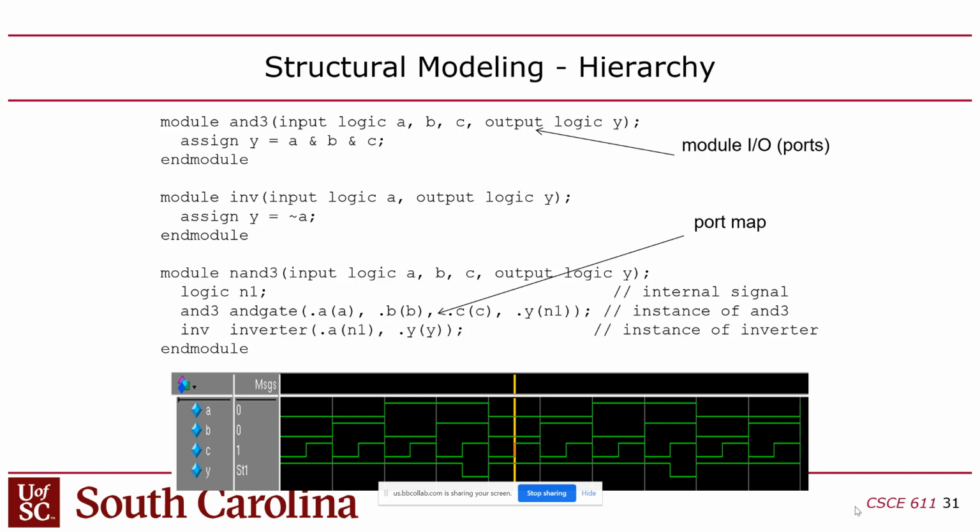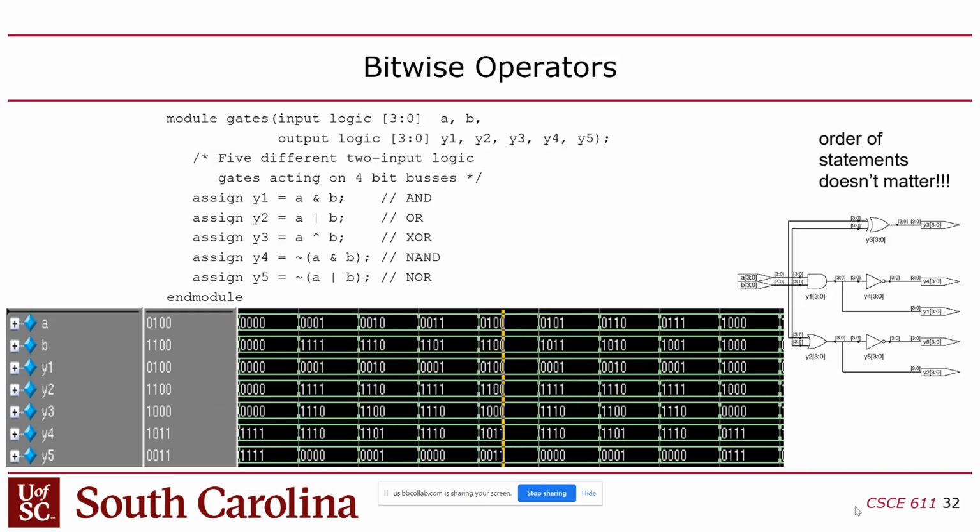But yes, I have actually read the Verilog spec, and I think there are 13 different possible voltage levels, including the ones you talked about earlier, like tri-stated or don't cares. They actually have, I think, 5 different strength levels, and that is one of them. As far as we're concerned, though, it's just 0 or 1 or don't care. The point is, don't get too concerned about that. It's not a problem.